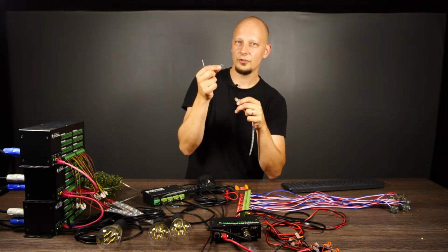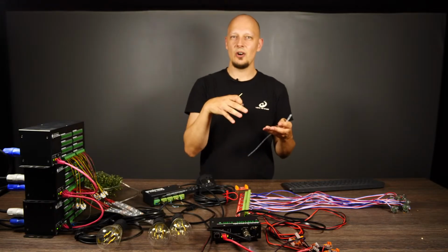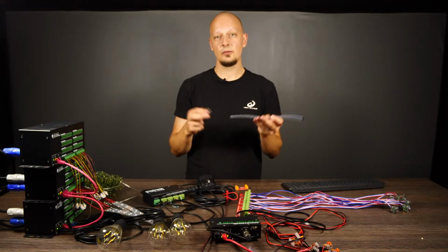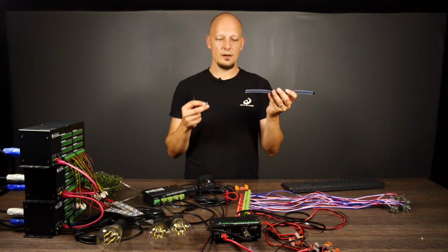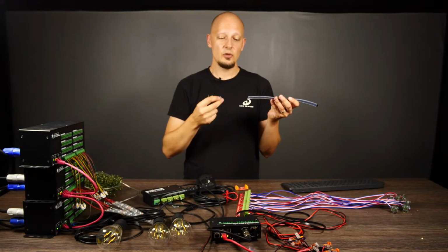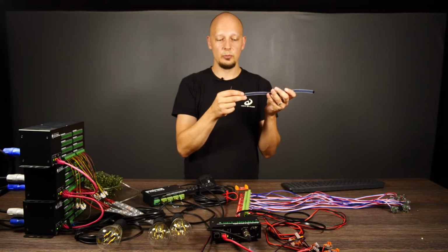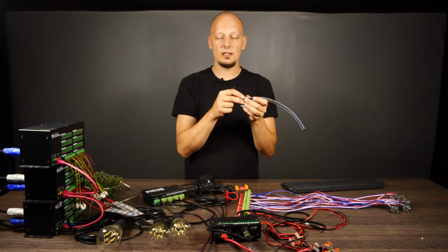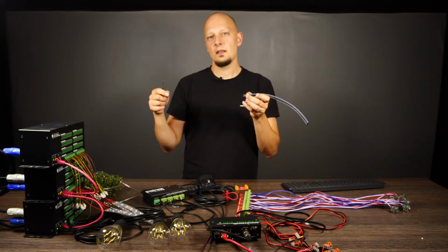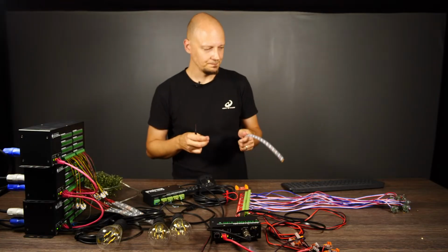You always solder this at the end of the strip, so at the beginning of the signal that you want to boost. So if I've got two segments, one here and another one, let's say 5 meters away, you want to place your TTL buffer at the output so that it will boost the signal, and that signal will then be able to travel even such distance.